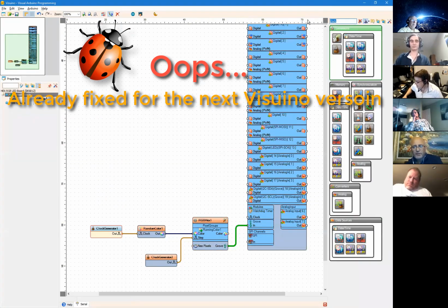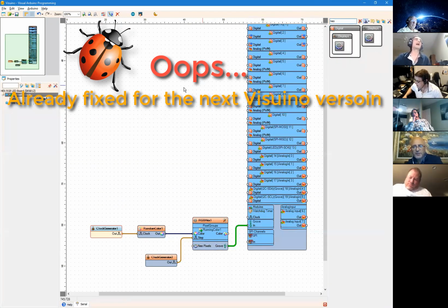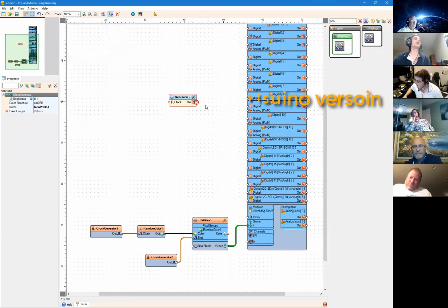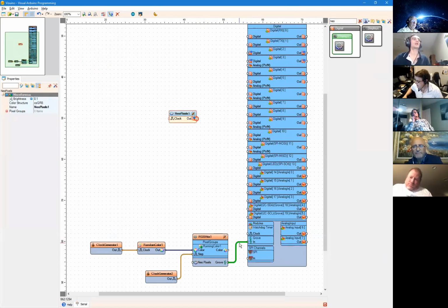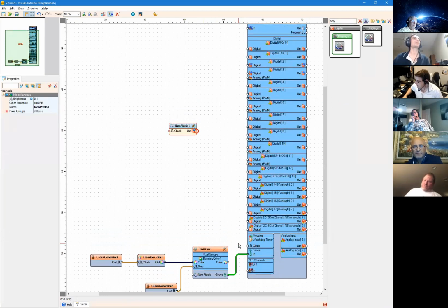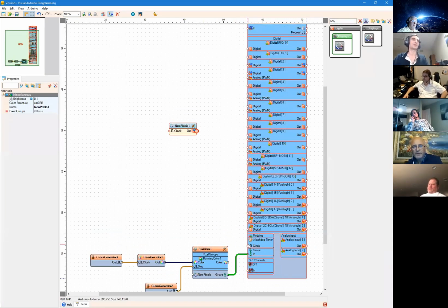Can you debug, use single stepping and breakpoints? Not in the Arduino IDE. When I say the Arduino IDE is super primitive, I mean it. The actual code is running on the Arduino controller, so you can only output log messages back to the IDE. Correct.